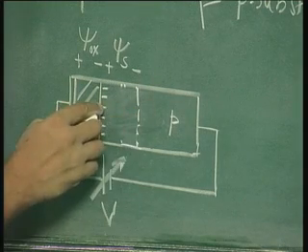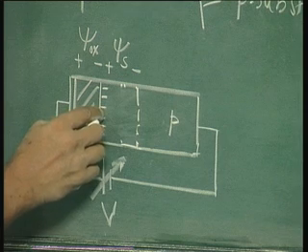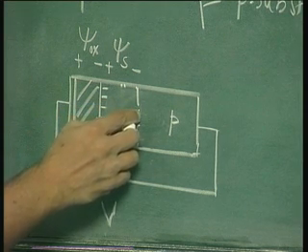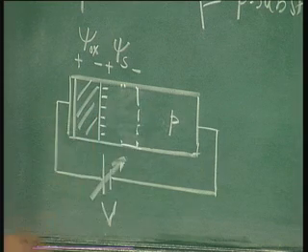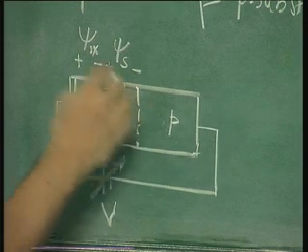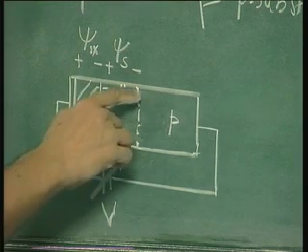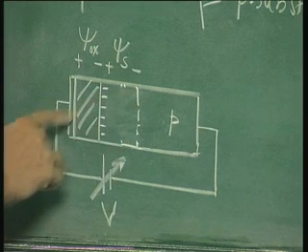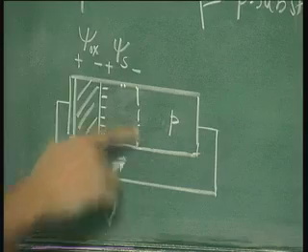It is difficult to get change in charge by moving the mobile minority carriers, but mobile majority carriers can be very quickly changed in concentration. Therefore, at high frequencies, the change in the charge in response to the change in the charge in the gate comes from the edge of the depletion layer.